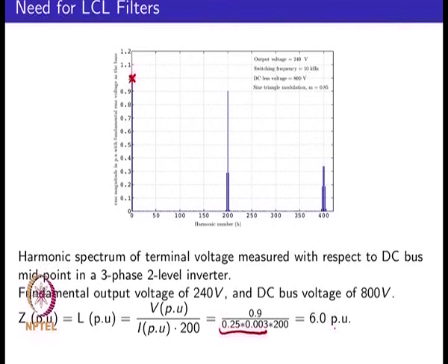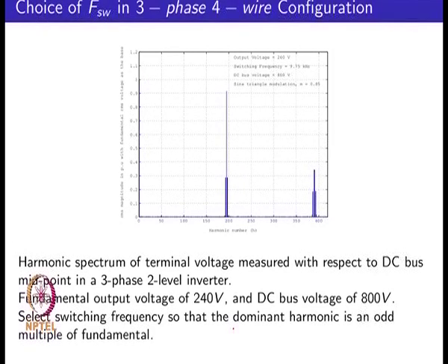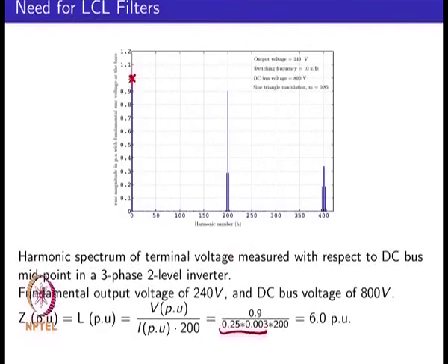One thing to keep in mind is that the even harmonics are restricted to 25% of the odd harmonics. This becomes especially important if your switching frequency is low, of the order of 1 kilohertz, which might be more common at very high power levels. So, it might actually make sense to shift your harmonics. For example, instead of 10 kilohertz, if it was 9.75 kilohertz, then that would correspond to the 195th harmonic. So, you could then eliminate the factor of 0.25 in the denominator over there.